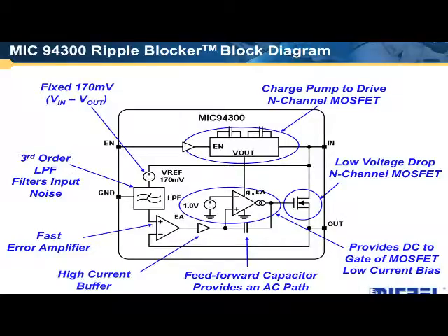The other thing is we need additional headroom to take care of any ripple at the input, because if you're operating that device just at the triode region, any perturbation on the input is going to upset your power supply rejection. So you have to have a drop here big enough to keep this in the active region and also to accommodate the kind of ripple you need. So this particular device has 170 millivolts, and it's good for blocking up to 50 millivolts of noise.